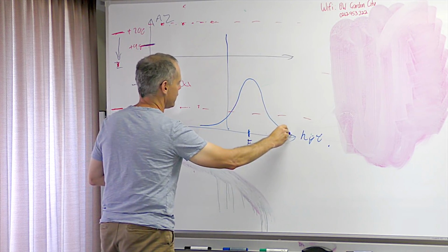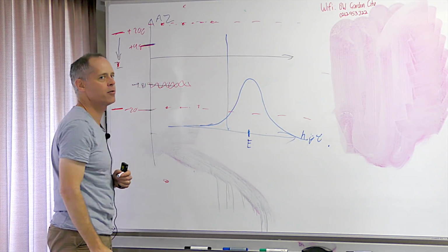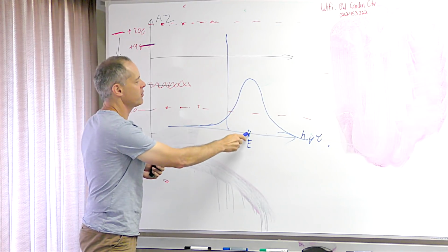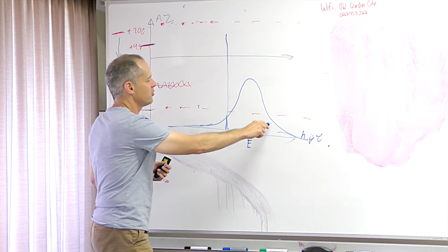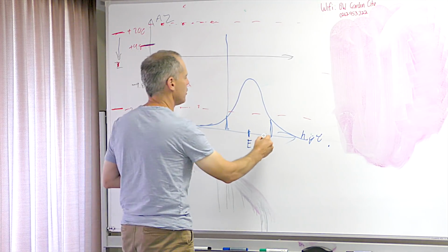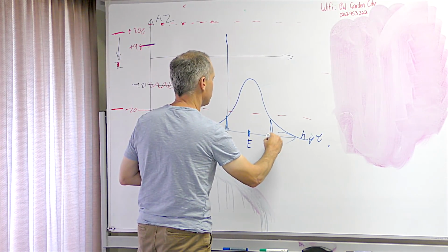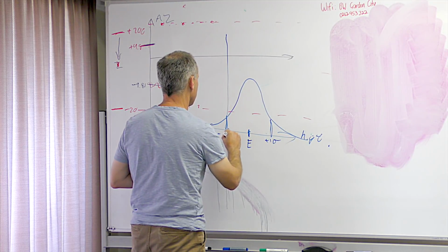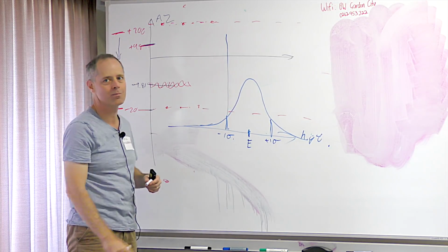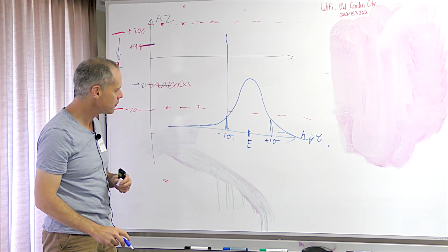In the extended Kalman filter formulation, we represent height as a statistical quantity with an expected value and a statistical distribution defined by a normal distribution, with plus 1 sigma and minus 1 sigma. Apologies to those who haven't covered statistics in the past.